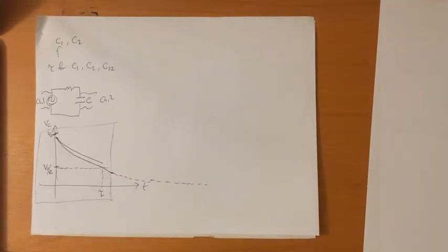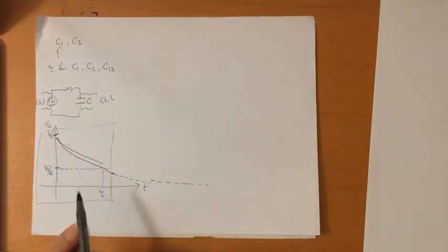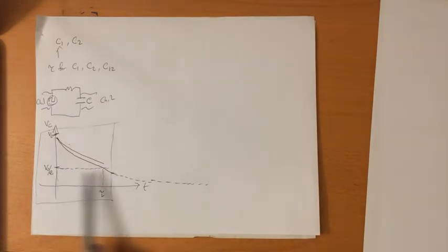I'm going to actually take you through the process of how that's measured with cursors. Unfortunately, since you don't have an opportunity to do this lab yourself, you're not going to get a chance to do this with cursors. This is actually one of my favorite exam questions. I usually give students an RC circuit to construct, and then they have to actually use the oscilloscope and use the cursors method. It's actually pretty quick once you get used to doing it, to measure the time constant.